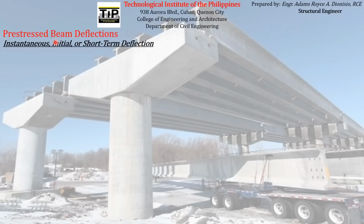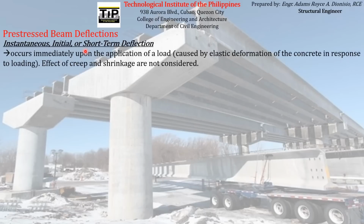So this first type of deflection that we are studying here are the deflections that are being experienced by the concrete beam or concrete element immediately as it supports the loads that are supposed to be carried by it. Again, these deflections occur immediately upon the application of a load, which are caused by elastic deformation of the concrete in response to the loading. So the effects of creep and shrinkage are not considered here, obviously, because the effects of creep and shrinkage are